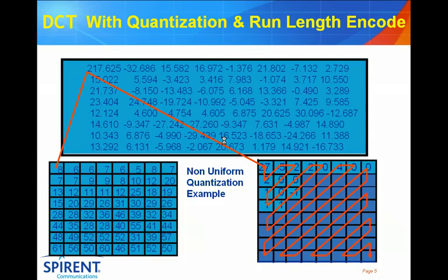Finally, we apply Huffman encoding, which is a form of symbol encoding, and we greatly reduce the amount of information transmitted in the signal. Now, of course, we do have a lossy picture. That is, we've compressed the picture, but we can never quite get back to its original form. However, hopefully, by reducing the amount of high-frequency components within the picture, we can fool the human eye into believing it's still a high-quality signal.